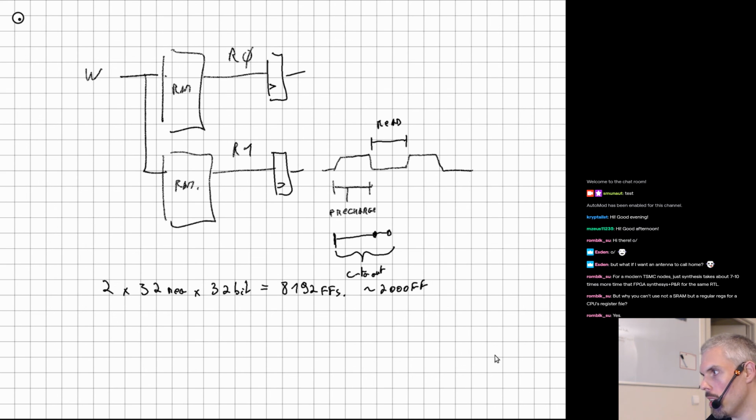So the downside of letting users do it is, first, it's much bigger, and also if you let the tool do it entirely automatically, it can have difficulty routing, because it will distribute things not entirely randomly, but it's not necessarily aware of the very repetitive structure of a register file and a way to create it in a neat array that is easily routed.